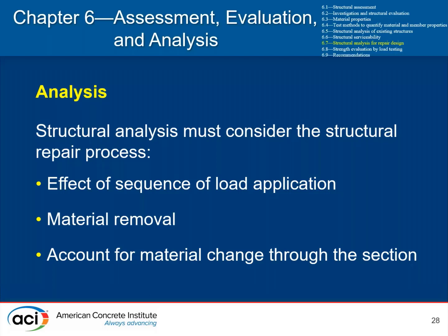And so the removal of that material can potentially shift and redistribute load that can create overstresses in adjacent areas, or redistribution to impart deflections, etc. So as part of the analysis, the effect of that material removal, as well as the effect of the sequence of the load application and what it means when the area is removed in order to conduct the repairs, is of critical concern.